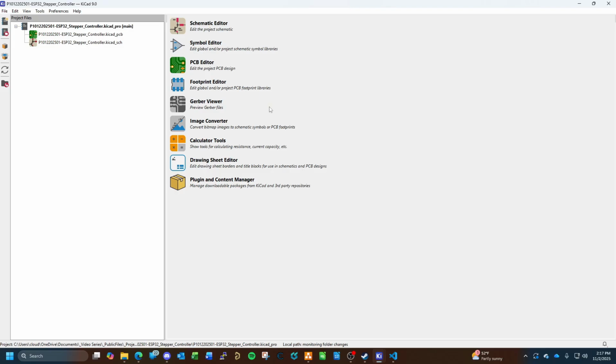Okay. So the way I prefer to work, I've noticed with my initial testing of KiCad, every part has its own library file. I don't like that. I think that's the hardest thing to administrate. When you're trying to pull in parts to do a design, having to select, oh, I have Texas Instruments parts over here, Analog Devices over here, Yageo resistors over here. I don't like doing that. I like keeping it simple with maybe 3 library files. One is for all your general parts, one is for connectors, and one is for logos.